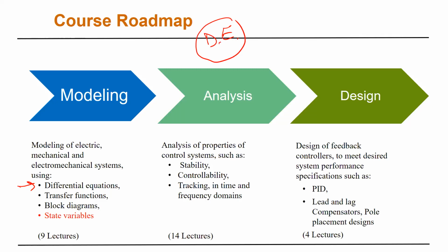Circuit, for example. What do we do? If I have, let's say, 2 capacitors and 4 inductors, and I want to get the differential equation model, what do I do? We use the relationship. Yeah, through what? How? What did we do? We use the nodal analysis or the mesh analysis for the circuits, and for other systems like the mechanical system, we use Newton's second law. So we have certain laws, we apply them.